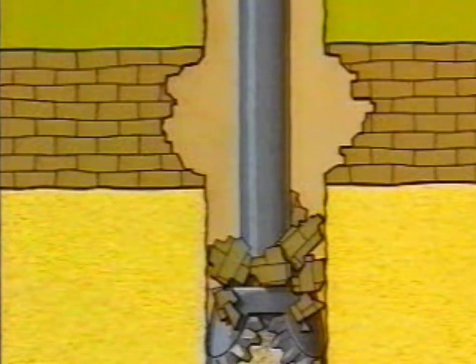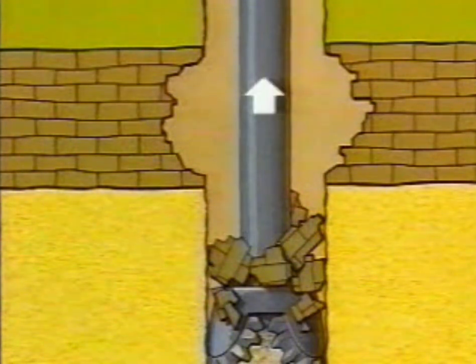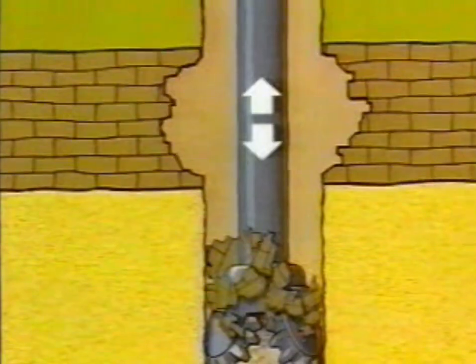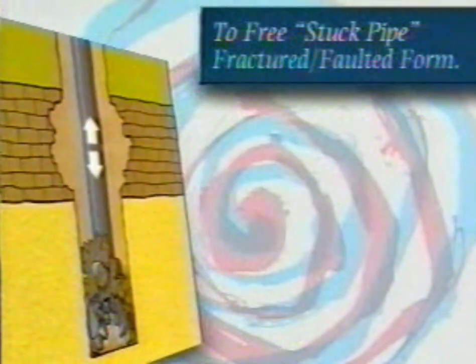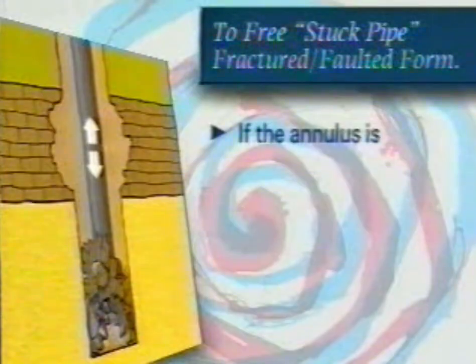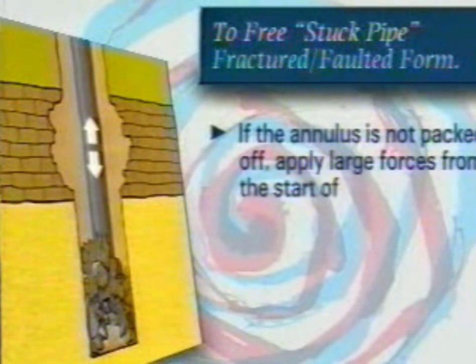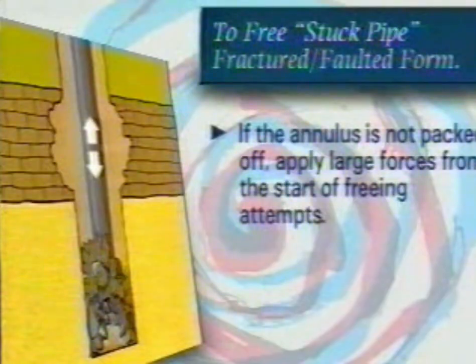In this situation, the string must be worked up and down to disturb or break up the obstruction. In addition to this, should the annulus not be packed off, apply large forces from the start of any freeing attempts.